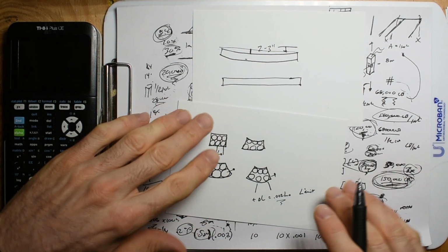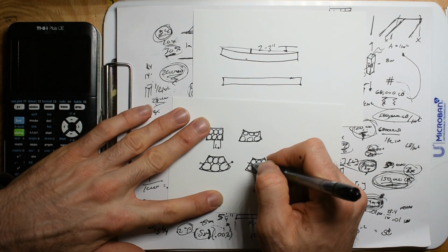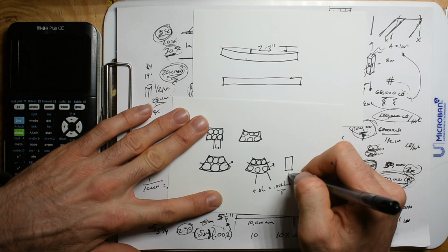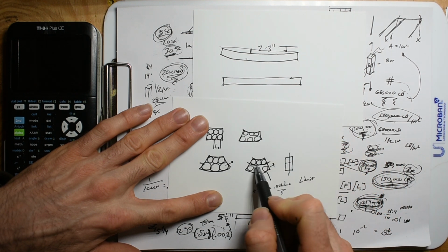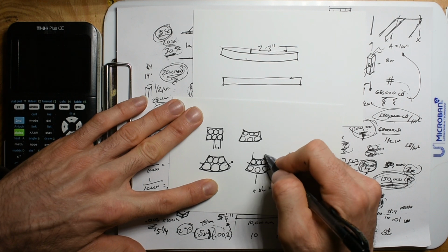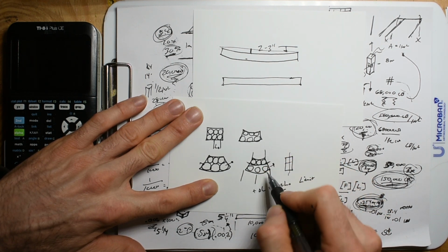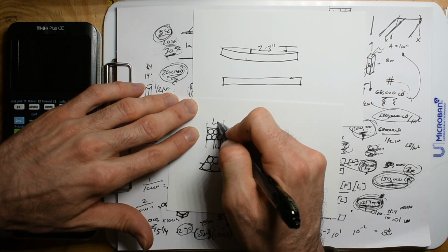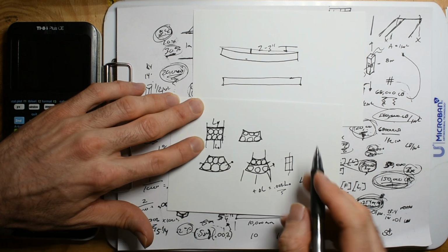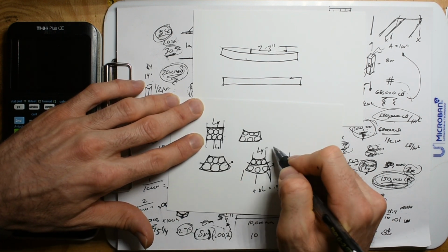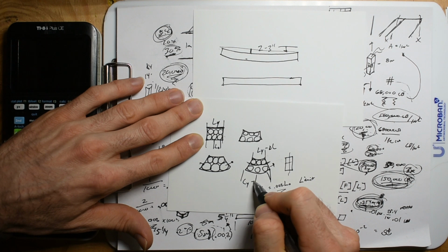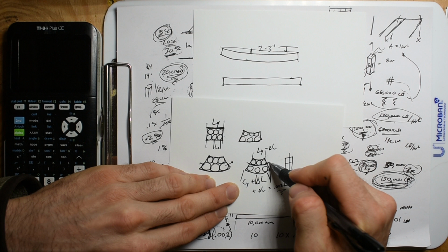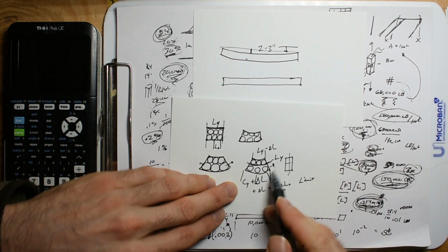All right, and we're almost ready to end this video, but there's a concept that right in the middle, as long as the beam cross section is the same, right in the middle there will be no change in length, because we had squashing of the top, lengthening of the bottom. The original length of the beam, we're just going to call it Ly, that's going to be that length, and then this is Ly minus a change in length, and this is Ly plus a change in length. Sorry to call it Ly, but anyway, right in the middle is just the original length.